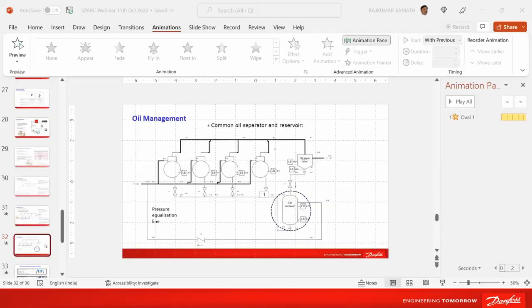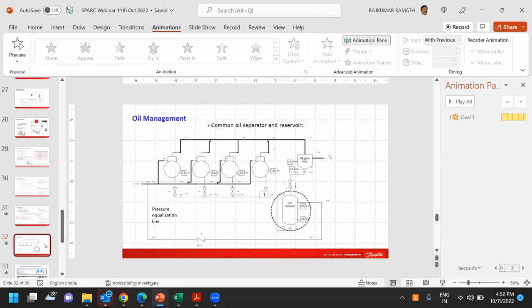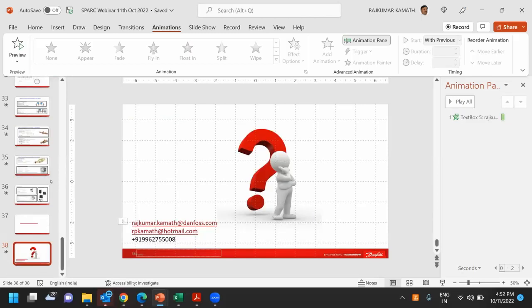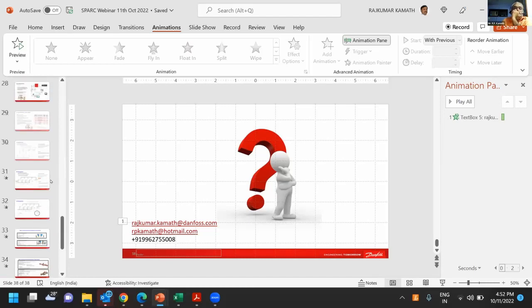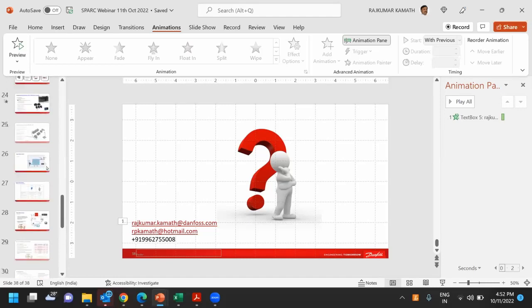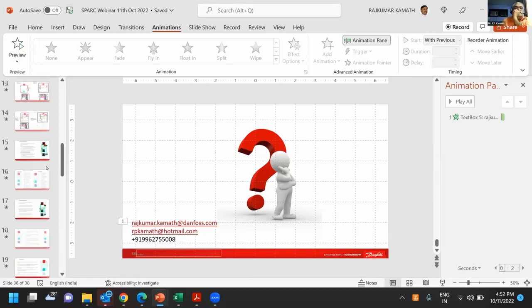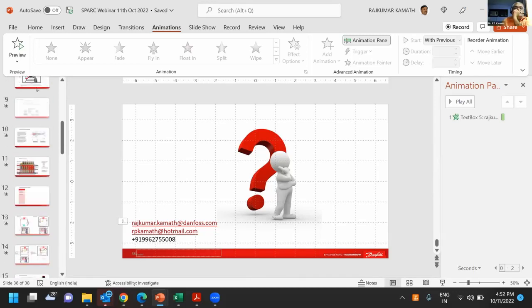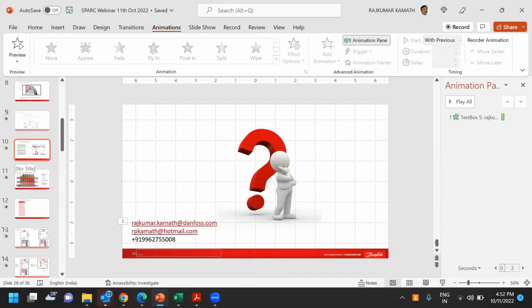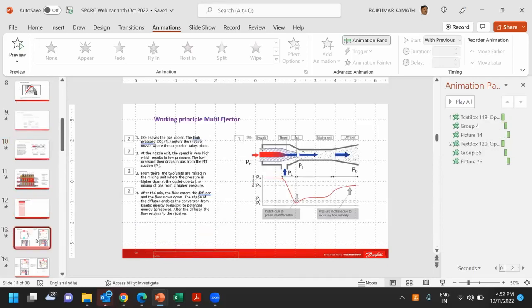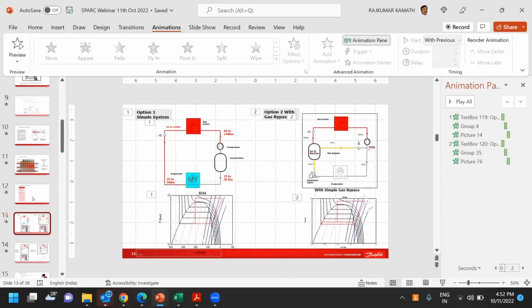I will have a small clarification again. If there are no other questions, I will proceed with my doubt. The gas cooler pressure is to be optimized, and you have got the line. You optimize the pressure line there. So you take the gas cooler exit temperature or air coolant temperature and control the pressure.